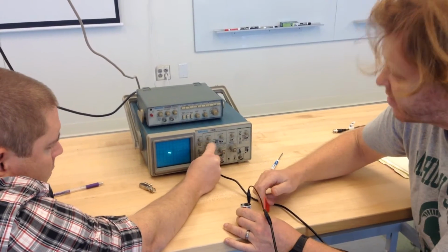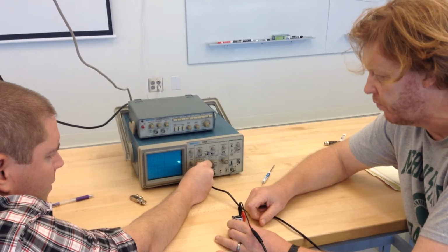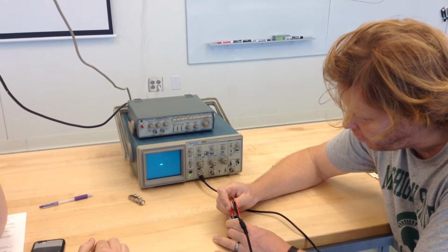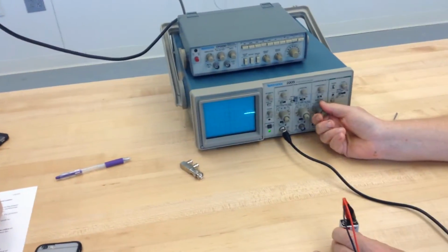it went up too high. Oh, it's 9 volts, so it goes up 4 divisions. So change it to 5? Yeah, change it to 5 volts per division. And this will jump up 2 divisions. See? Up. Up. Let's make it go by even faster.